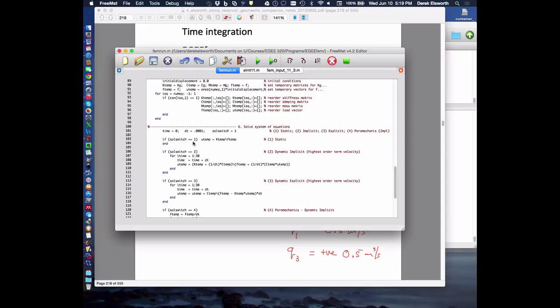So all it does is it uses a switch that you set to some magnitude, and that defines whether you solve steady state, which is what we just did, or whether you solve it with implicit time stepping, or whether you do it explicitly. So I think we just probably have to change this. And I'm going to change it to 2 to be able to run it. And I guess we have a time step in there. Well, let's leave that time step and see what it does. Hopefully it runs for a number of steps rather than just forever.